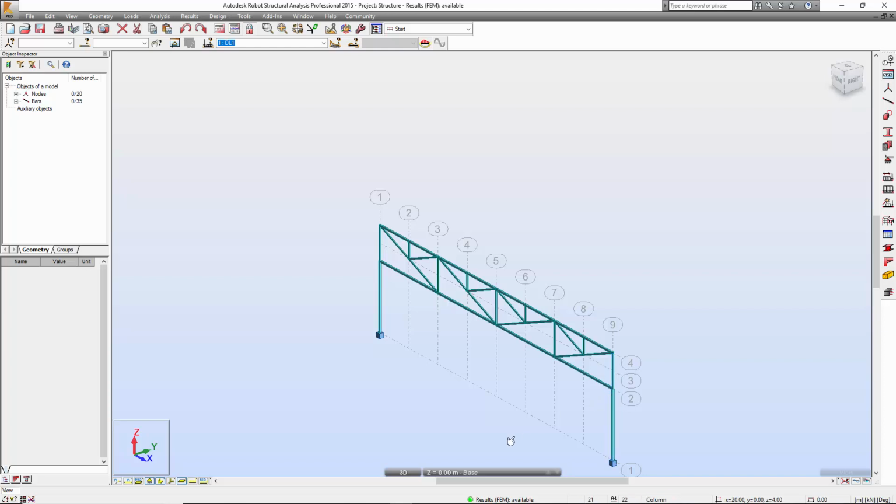So what the structural engineer is required to do is that the stiffness of the beam you put in should have exactly the same stiffness as the column. In other words, if you apply the loading on the top of the truss, and this joint moves 1 millimeter down, then the new beam coming in to support this truss should deform under the same loading exactly the same 1 millimeter as well.